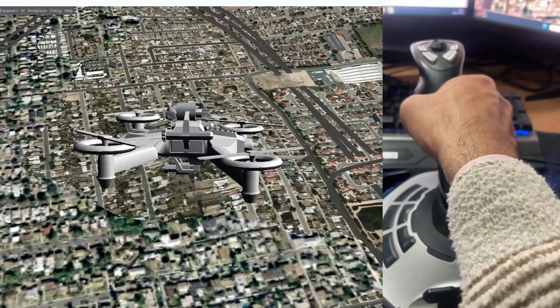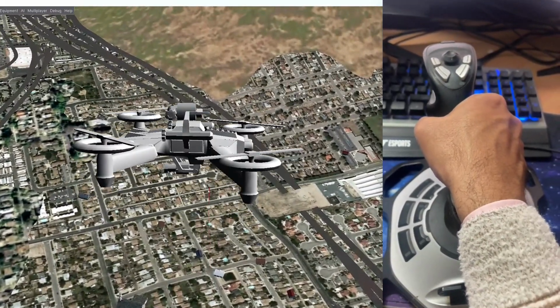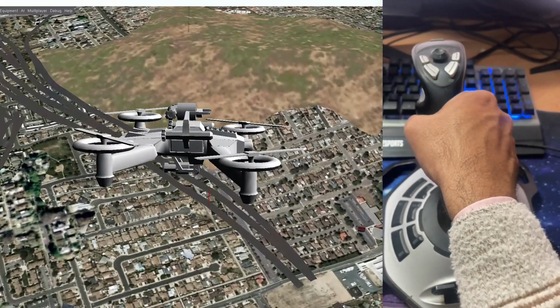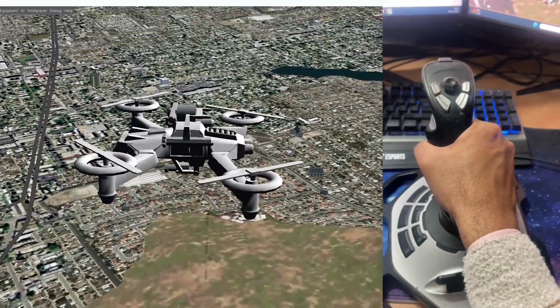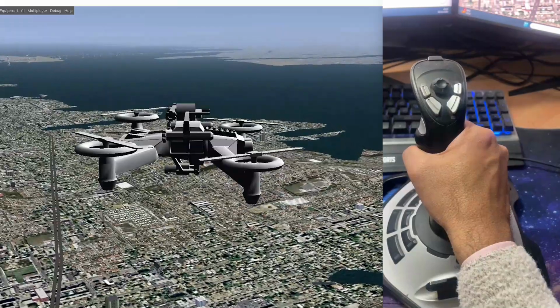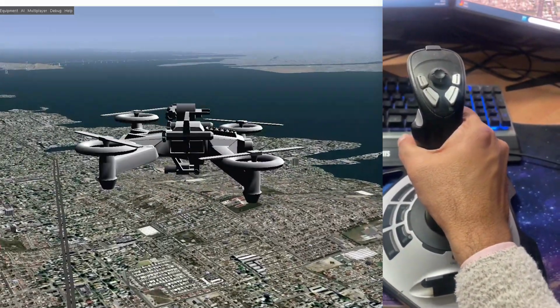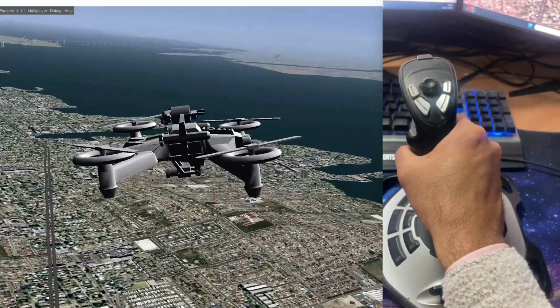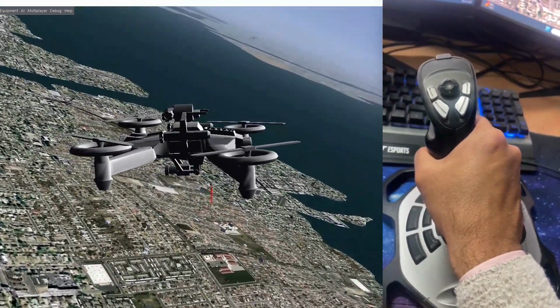Full pitch down, close to the ground. Now when you release the stick, the quadrotor pitch will become 0. That is the beauty of flying in this kind of mode. And when you take a roll, see this full roll.